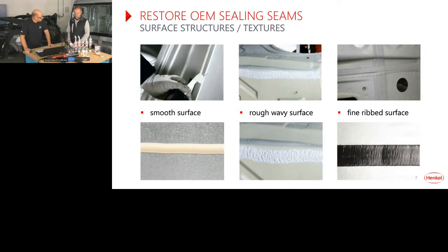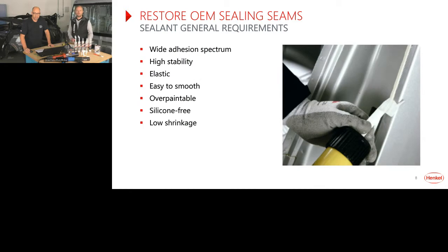What else do we need for the right choice of the sealing product? I guess the properties of the product should also be kept in mind. We have seen in our survey that adhesion is very important. So we want a sealer material which has good adhesion on a wide range of substrates. We have E-coated panels, painted panels, and bare metal panels.